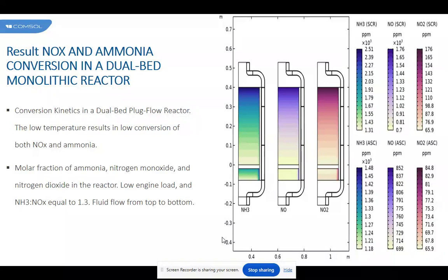Monolith type substrates are extensively used in automotive catalytic converters and have gained popularity in several other industrial processes, owing to their advantages over traditional unstructured catalysts such as large surface area and low pressure drop. Novel monolith configurations have not been investigated in depth. In the simulation, we use a detailed computational model at the reactor scale which considers entrance length, turbulence dissipation, and internal diffusion limitations.